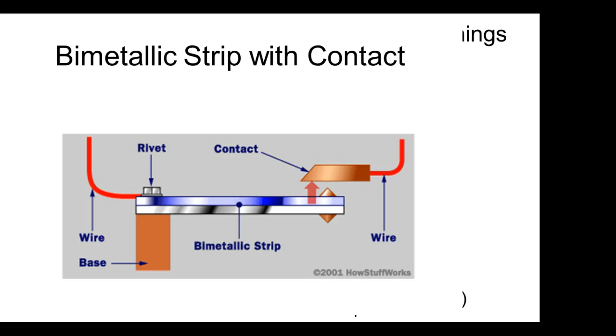So this is pretty straightforward, with contact. A lot of times, like on a circuit breaker, they set this thing out. I need to bring one in. They're hard to take apart. They rivet it together, and usually when I'm trying to drill the rivet out, something happens. But it's got a spring that's pushing on it too. So when it bends, it pushes and the spring snaps down, and then it latches in the open position on the circuit breaker. And then you have to reset it.